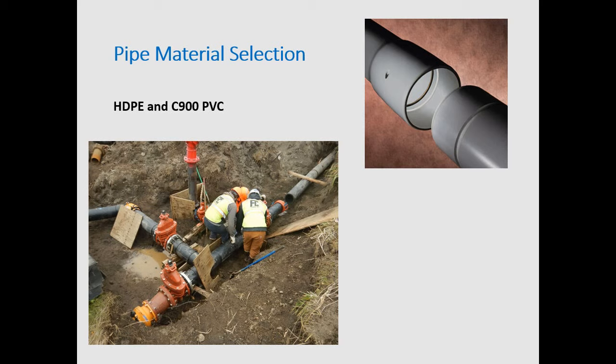Through the design process, we used those contaminated site maps and identified where the known contaminated sites are. We incorporated in the design extra petroleum resistant pipe material so that it's on site. If they find unknown contaminated sites, they have a mechanism to still have pipe out there. Again, to ship out 29,000 feet of pipe, if you only have 29,000 feet and you have to switch out 1,000, that's really expensive. So it's all part of the bid process. So that's what we did. We have both on the design bid build: both HDPE and PVC.